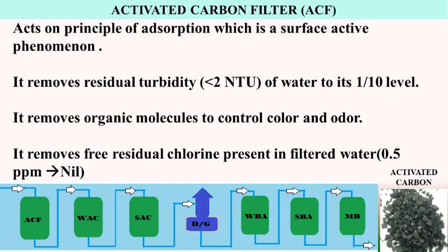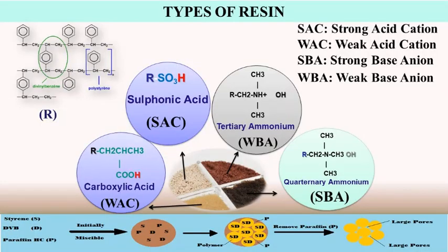Affinity and attraction are due to electrostatic force that is created by ion exchange arrangement, or physical forces, that is van der Waals forces, free movement within the system, or chemical interaction, surface attachment type. All these types of forces impact the process. Activated carbon filters are the first inlet stage of the ion exchange process, the demineralizing water treatment process.